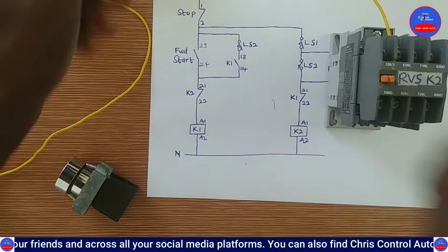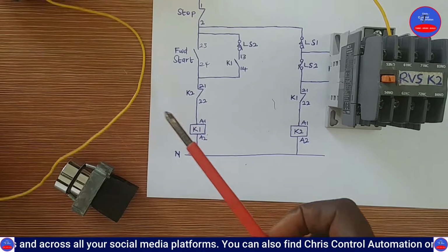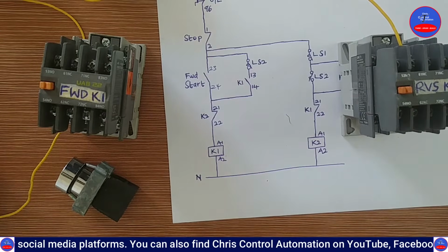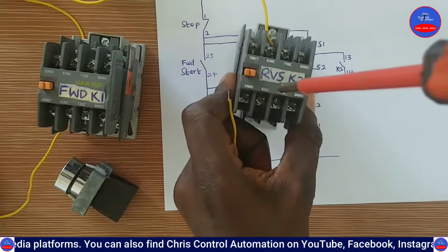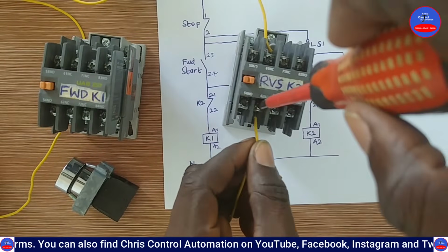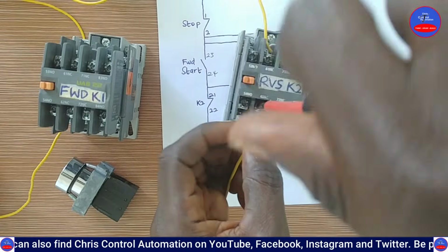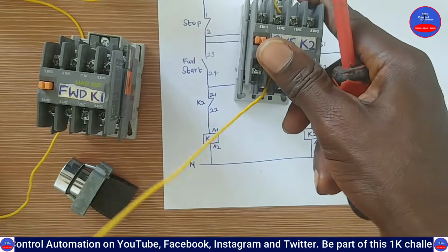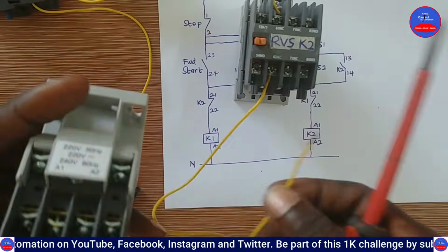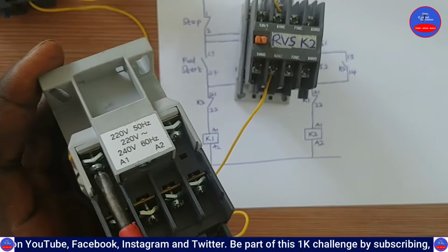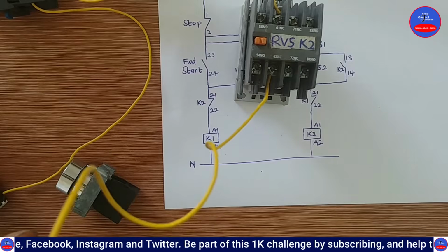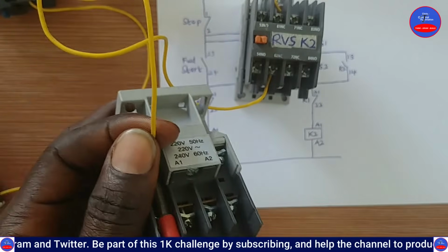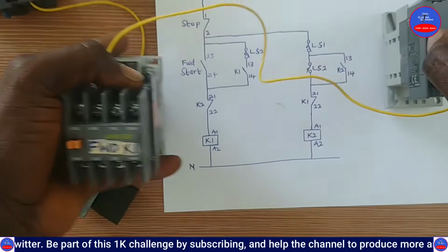All right. From the down one, go to the contactor 1 coil. This is our contactor 1. Goes to the coil. So from this side, seeing it, contactor 1, this is contactor 1, the coil, that is the A1. Okay, that is the A1.